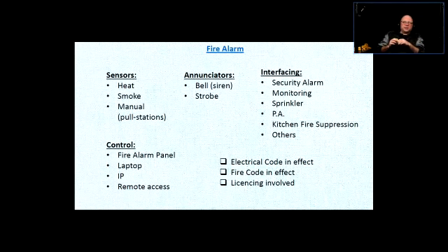Well, the wet systems trigger quicker. The water comes out quicker, but they can only be installed inside of a building that has normal heat in the winter and so on. But let's say it's a sprinkler system installed in an outside garage, for example, a hospital has a huge outside garage where you can park your car, and there are no walls. The whole thing is basically exposed to the outside elements. So if there was water in that, then in the winter the water would freeze in those pipes.